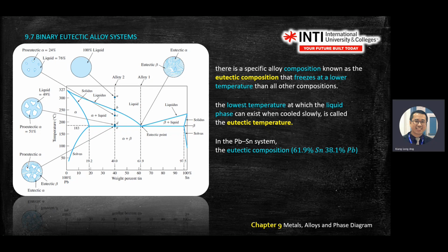Okay, the concept is important. Once you understand what is eutectic, then the rest is fine. The graph can change. Then you read the percentage, the eutectic composition. Like on the graph that I drew on the whiteboard here, you just drop down here and find the percentage of copper. So here it will give you the percentage of copper, let's say 10%, and also 90% of nickel, for example. Okay. It depends on what the question wants to ask you.